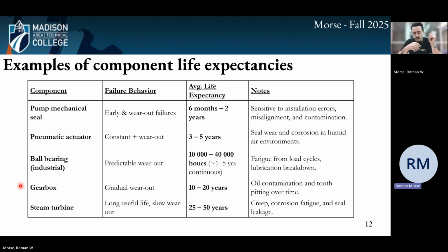There's a fluid inside of the gearbox that's supposed to lubricate and help minimize the amount of degradation to the gears inside of the gearbox. But it also holds all the debris. So if it's not regularly cleaned out, then there are all these chips of metal floating around in the oil.